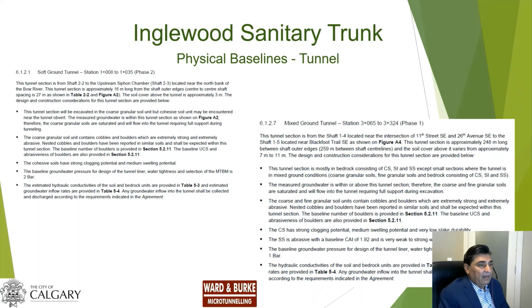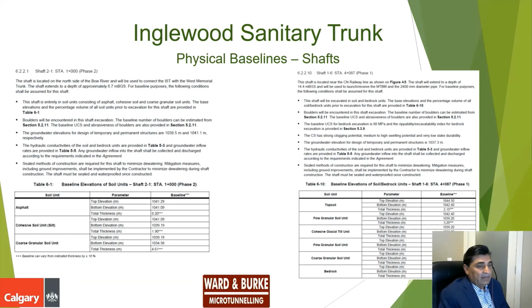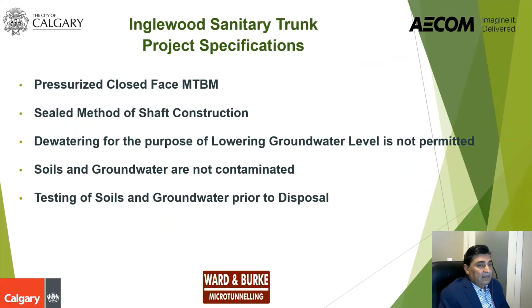Then we provided baselines for each tunnel section, and we provided baselines for each shaft. So after providing all those baselines, we went one step further, because we know the ground is very challenging. Open face machine is not suitable. Dewatering is not practical.